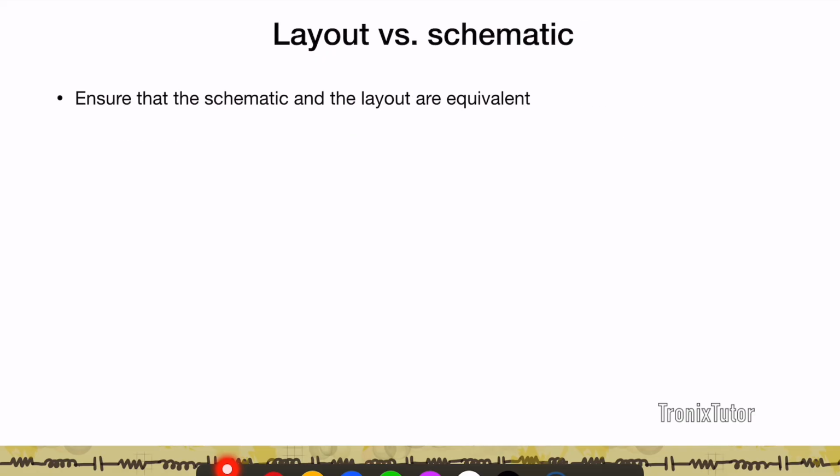And remember that a lot of our flows are automated. As I told you, you write an RTL design and then the tool comes in and converts it to a gate netlist and eventually standard cells. And most of the digital designs run this way, right? Now, obviously, if it's something which all competitors are going to use, then you're going to see that there isn't a lot of difference in design. So obviously for critical parts, you're going to try and see if there's some way by which you can make your design more competitive, right? And that would involve sticking cells closer, playing around with the spacing rule somewhere here and there. So eventually you're going to be editing some of your layouts, right? Again, to make your design competitive.